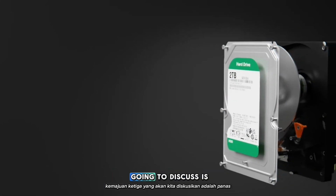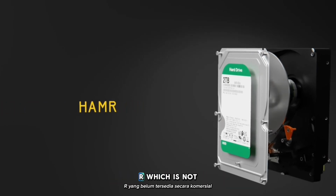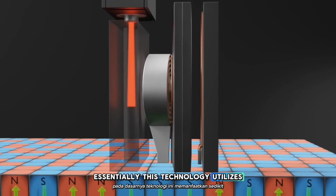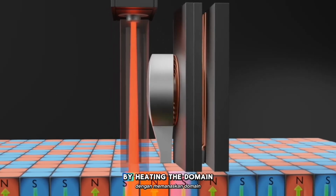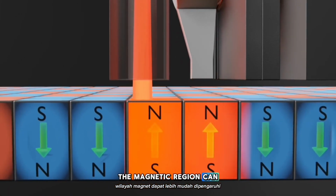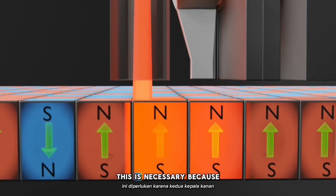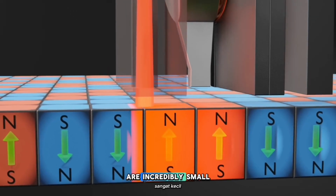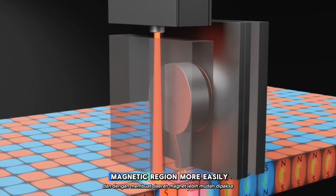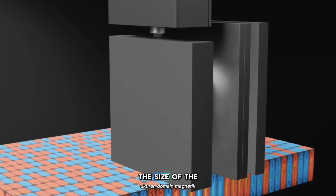The third advance we're going to discuss is heat-assisted magnetic recording, or HAMR, which is not yet commercially available. Essentially, this technology utilizes a small, focused laser to heat the region that is actively being written to. By heating the domain, the magnetic region can be more easily influenced or coerced to orient in a particular direction. This is necessary because both the write head and the localized electromagnetic field are incredibly small, and by making the magnetic region more easily coerced using focused heat, we can continue to shrink the size of the magnetic domains.